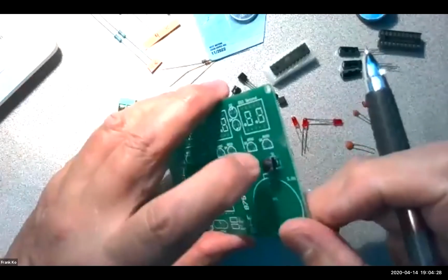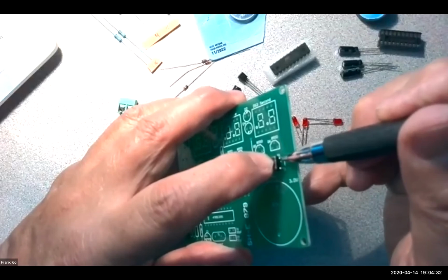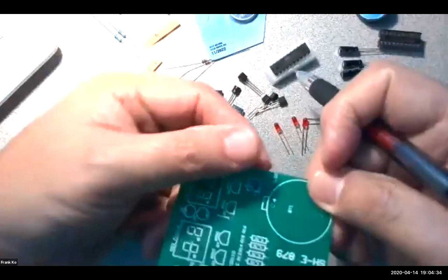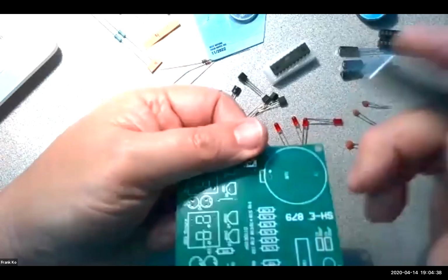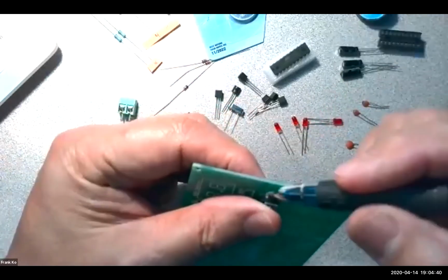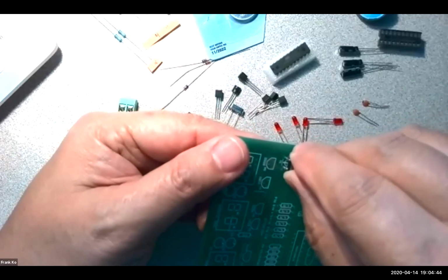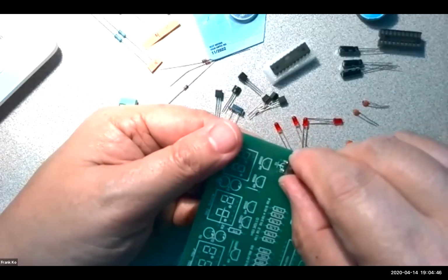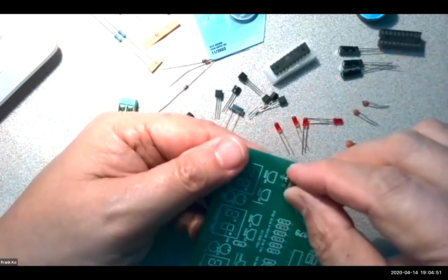What I mean to say is this switch has pins coming off of the right side and pins coming off of the left side, okay? Do not wire it up this way where the pins are at the top and the bottom. That will not cause the switch to work properly.